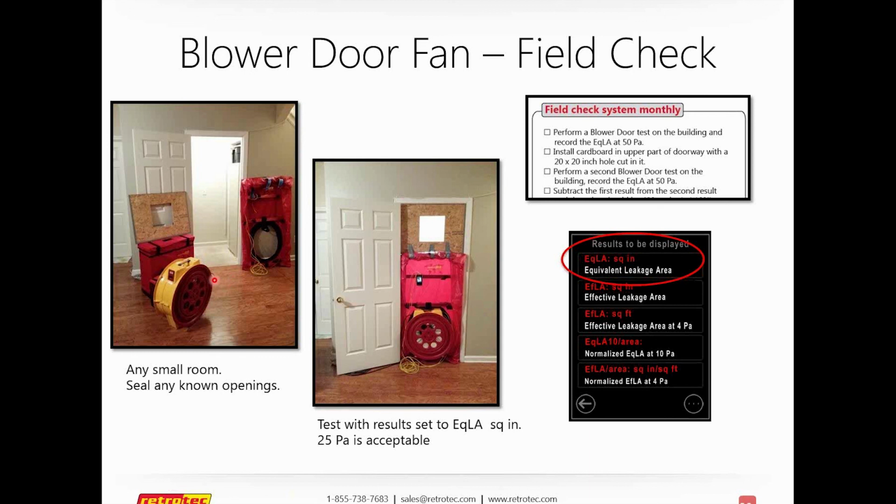So we've got all this equipment here, which is your blower door system, and this is a piece that we've made. Here I have a wooden board, but you can use a piece of cardboard, a really durable piece of paper, or corrugated plastic, anything, as long as it's flat. Then we cut a hole into this rigid piece of material, and we know exactly how big that hole is.